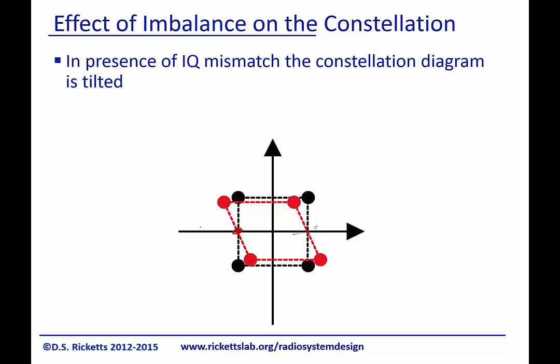So now one thing you might wonder is what happens if you have a complete 90-degree phase shift. Well, what's going to happen is this is going to move down here. These two are going to collapse, and this is going to move up here. And that makes sense because basically you're either going to have the two signals adding in phase to give you a high signal with a 0-degree phase shift. They're going to add in the opposite phase, so you're going to get superposition again, and then they might cancel one another where you'd have 0.